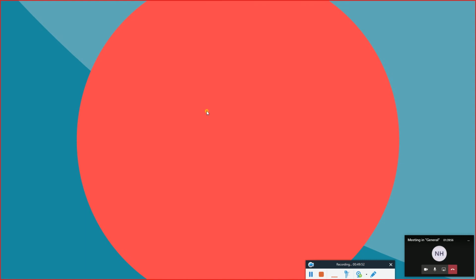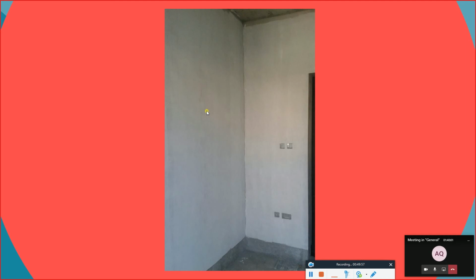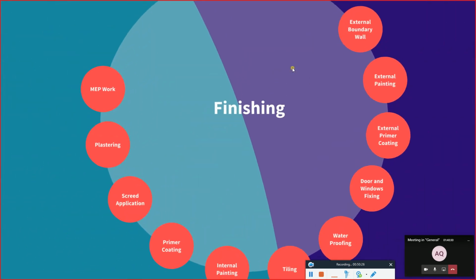Okay. In case you are going for painting, not tiling, normally we go for a primer. So you can see that we are having the primer here. It's not a paint, since painting will not be really effective on a plaster. Normally we use a primer. Okay, so this is a primer that we are using here. After that we can go and paint. So this is an example of internal painting.